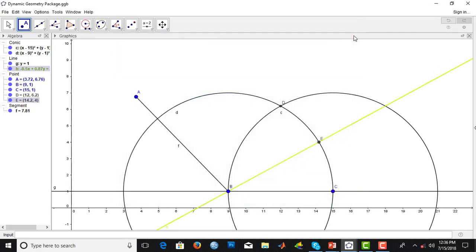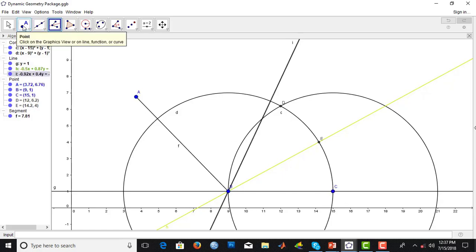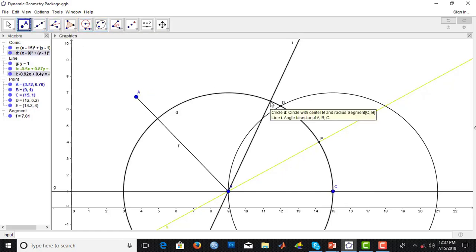Now, we do not have to measure the angle ABC. I just need to reduce it geometrically to a point of its submultiple angle within this configuration CE. I'll do that by multiple bisections. However, here I must be noting the number of times I draw these bisection lines.